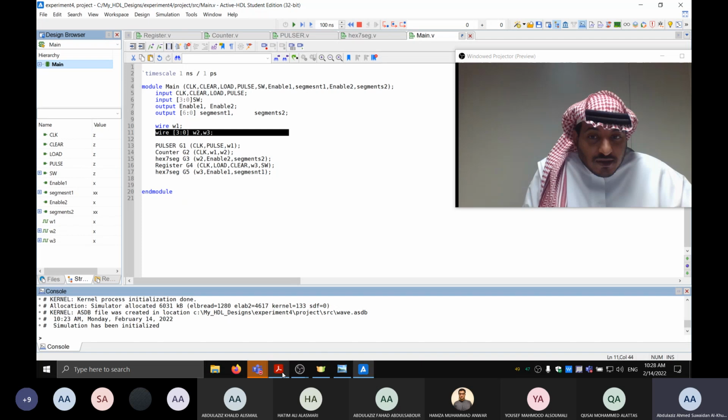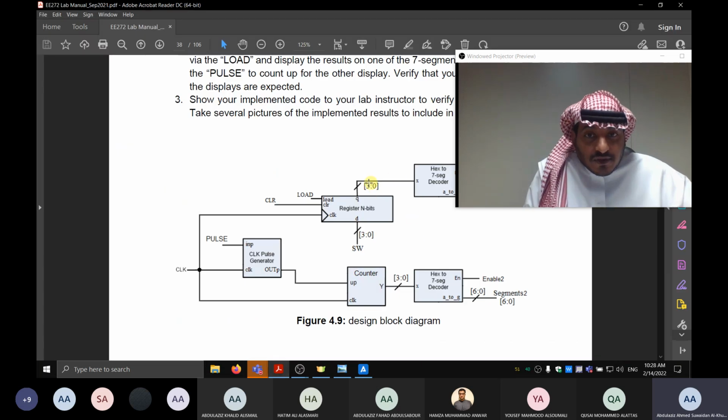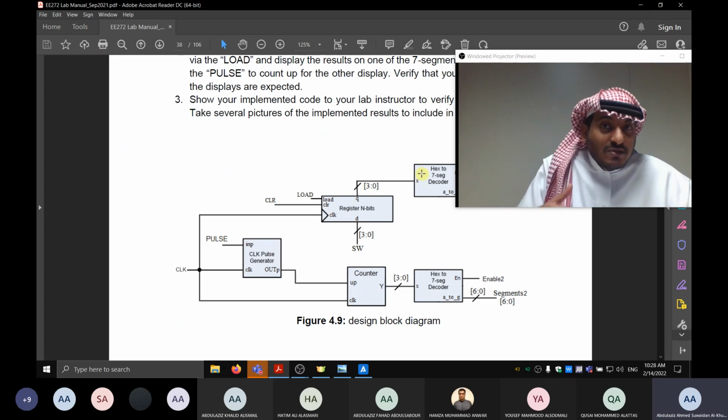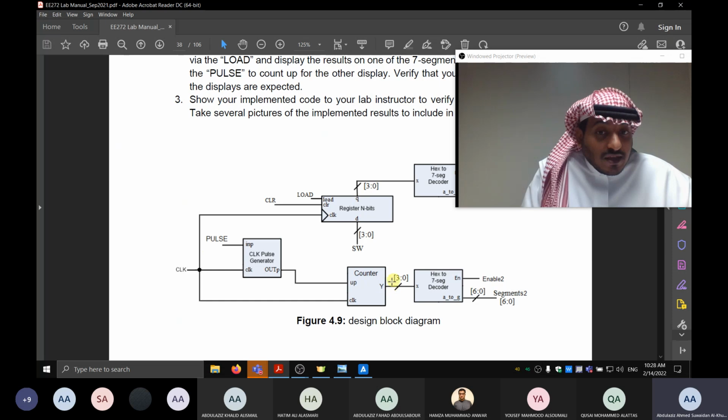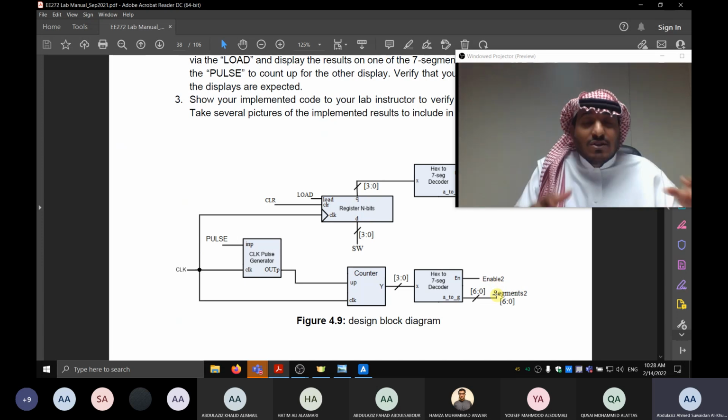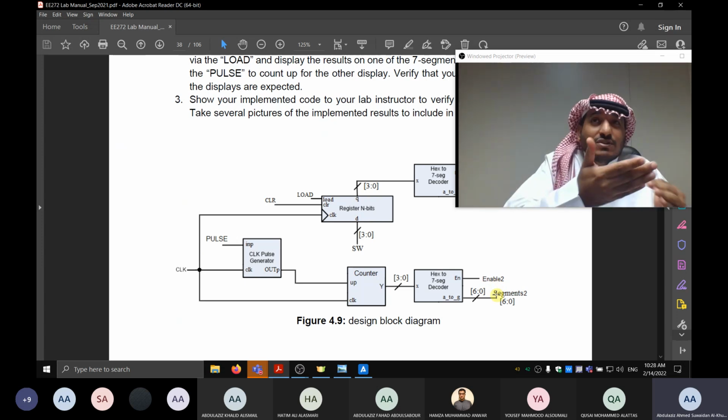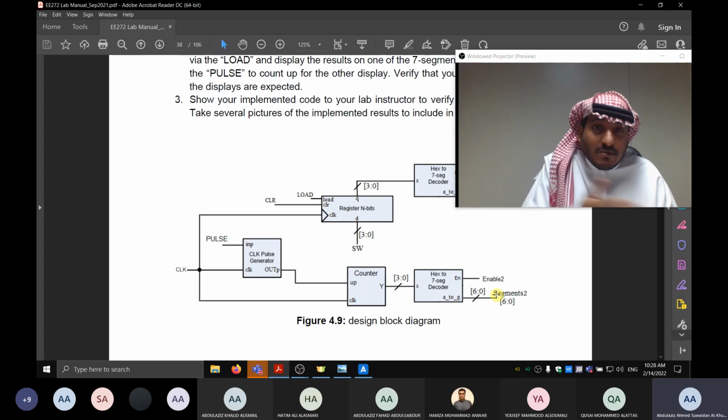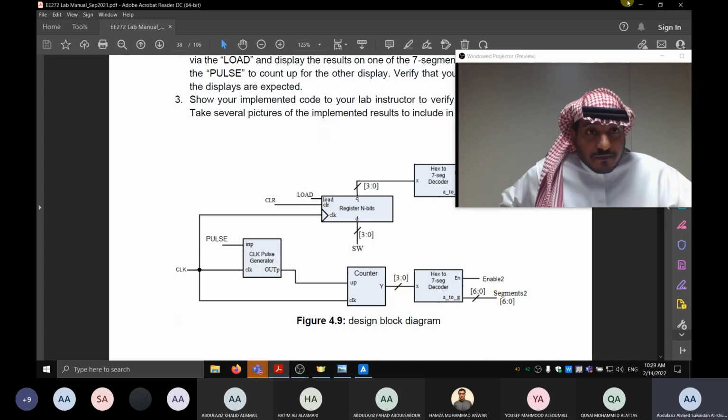So go back and only see the wires. Because I know the register output is 4-bit, I can understand it. No need to see after the coding. And then same thing for the counter. If you see only the bits, it's enough. The segments are just for the display itself. If you see something like 11101, you cannot understand it. You have to decode it and then convert it back to the numbers. It takes some time, but quickly, you can only see the wires itself.